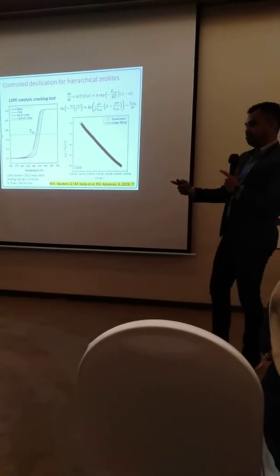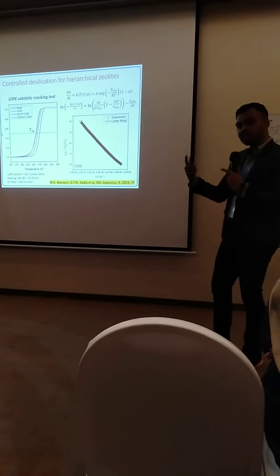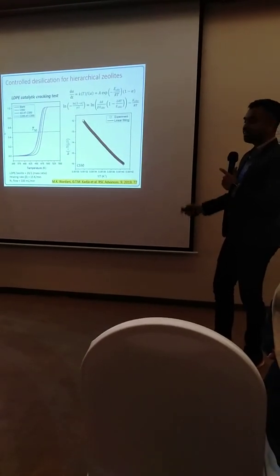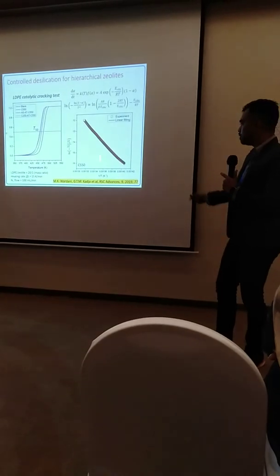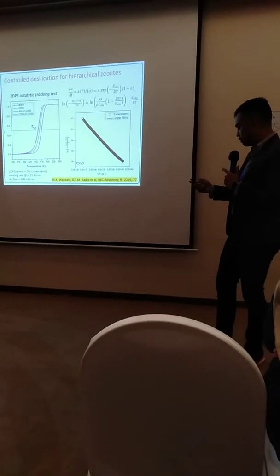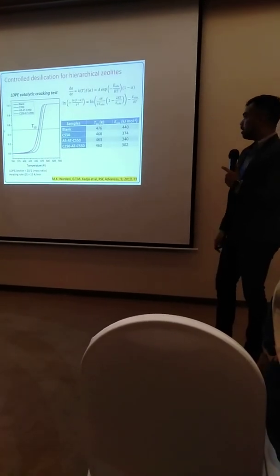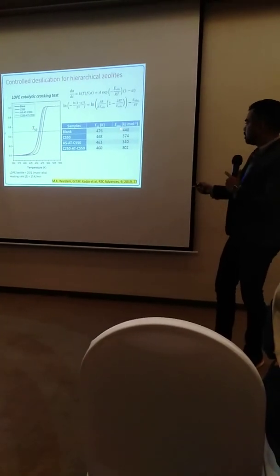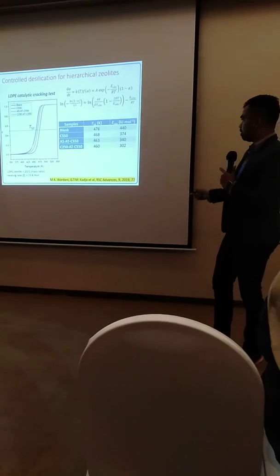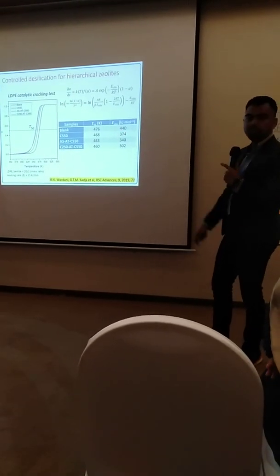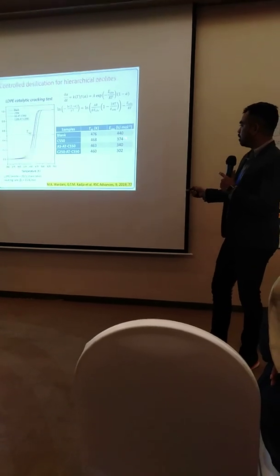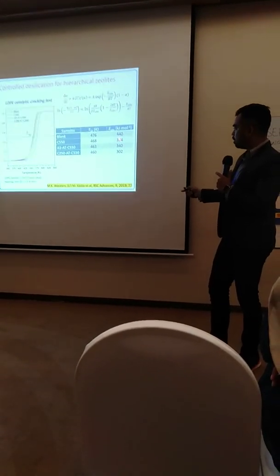We can calculate the activation energy for the LDPE catalytic cracking. See, this is the plot. The blank sample without the addition of catalyst has an observed activation energy of 440. But when you use the zeolite, it decreased to 374.